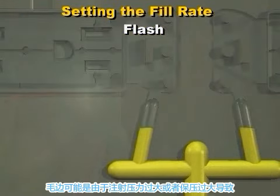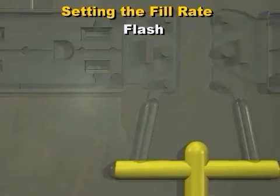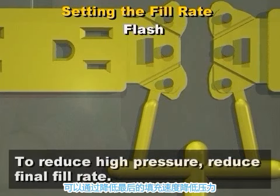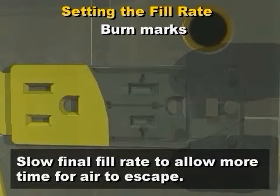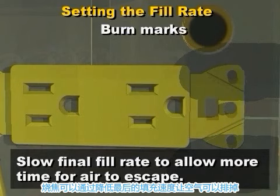Flash can be caused by either a high filling pressure or a high packing pressure. If a high filling pressure causes flash, this pressure can be reduced by reducing the final fill rate. Burn marks can be reduced or eliminated by slowing the final fill rate. This allows more time for air to escape from the mold.